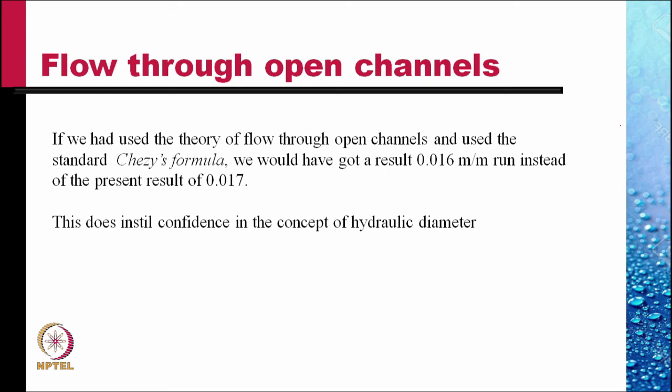So even though the open channel has a separate theory to deal with, we could model it as a pipe based on the principle of hydraulic diameter and get a result which is well within the range of accepted values. This shows the power of characteristic lengths properly used.